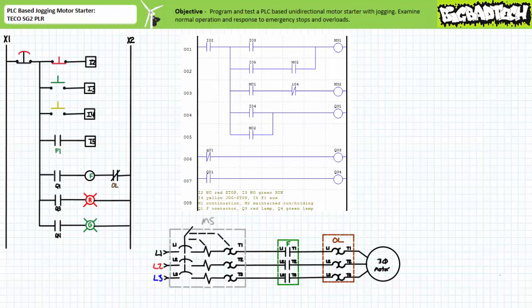If you, however, slow down and walk through this program line by line as would a PLC during several scans, you'll note the reason behind its construction. Virtual relay M1 is merely the means of continuing Rung 1 beyond the permissible limit of 3 contact entries allowed for this particular manufacturer. Virtual relay M2 in turn dictates whether the maintained run state has been actively asserted. The holding circuit in Rung 2 is established if and only if the F contactor actually closes and the maintained run state has been asserted.